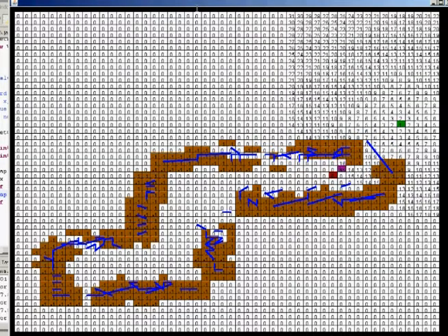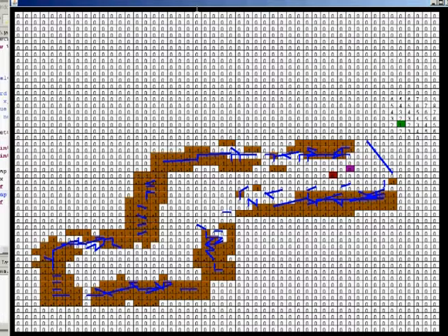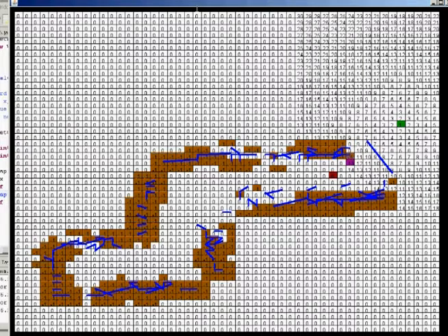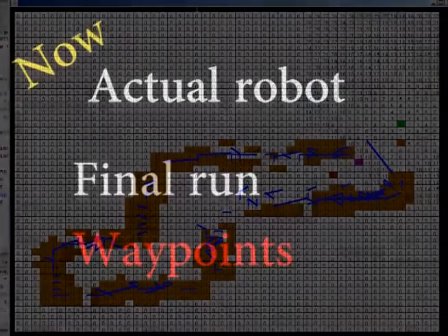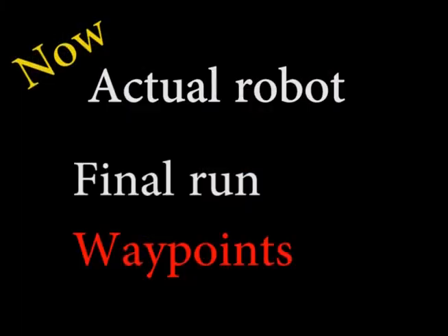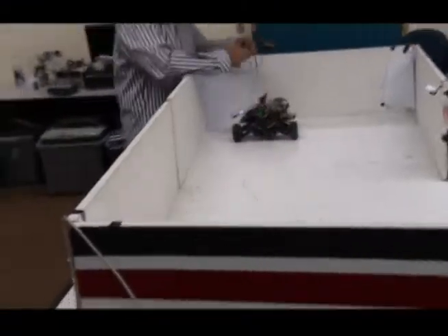If it's in the same while loop for a long time, it's going to sweep around 360 degrees and it's going to update and correct that blank space. After correcting that blank space, if it realizes there's a blank space, it's going to update the GUI and tell the robot to run the wavefront again, then we can follow that path again.